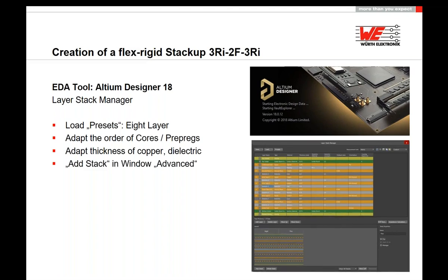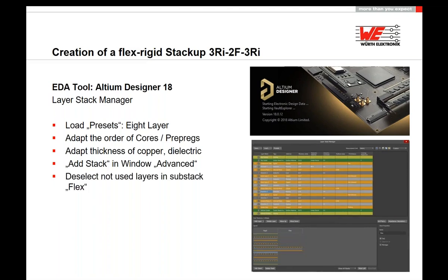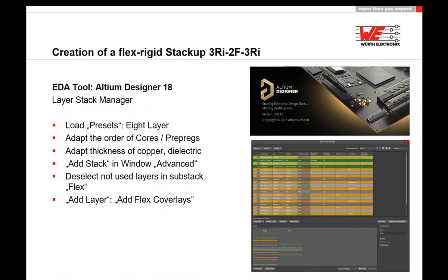And for flex inside, the standard looks like this. Again, the same mid TG material, TG150, polyimide without adhesive. And in the flex area, we are now using polyimide cover lay, only partially in the bending area with a small overlap into the rigid area. So this is the standard and the tooling box for building 4, 6, and 8 layers flex-rigid with inner layer flex.